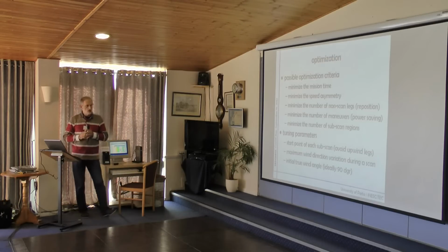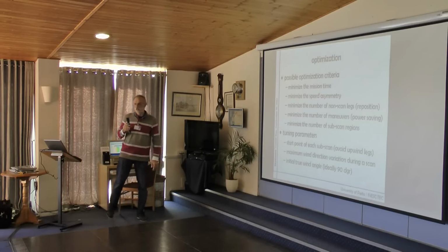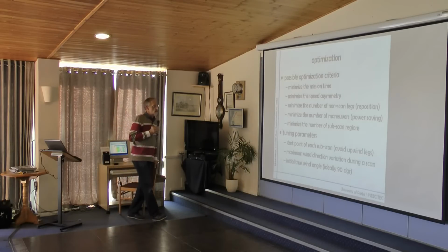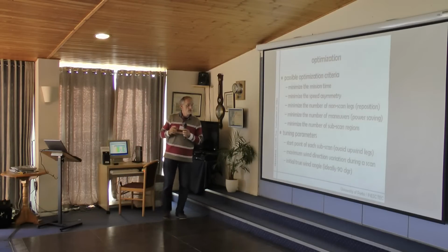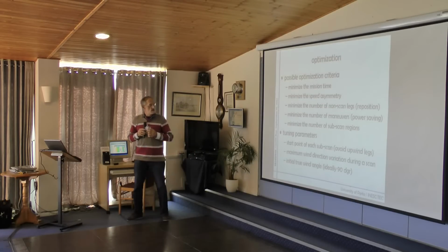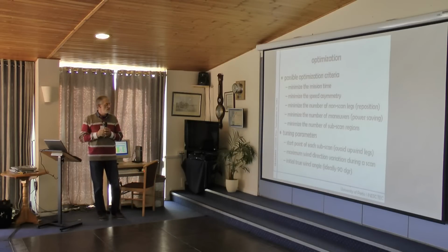Possible optimizations can be the total mission time, the total time it takes to complete the scan of the area. Minimize the speed difference between legs in one direction and in the other direction. Minimize the number of non-scan legs to reposition the boat for the next scan area.